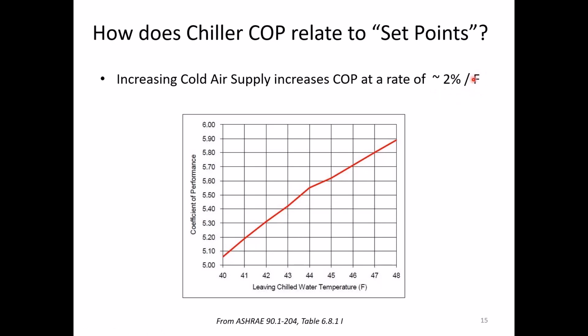So as you raise the return air temp or the leaving chilled water temp, your efficiency increases. And this is just what we were saying before about delta T. If the temperature coming out of the data center is high and your atmosphere is fixed, then the bigger that delta, the better the overall efficiency is, just due to the heat transfer equation. It's fairly straightforward, but it's powerful.